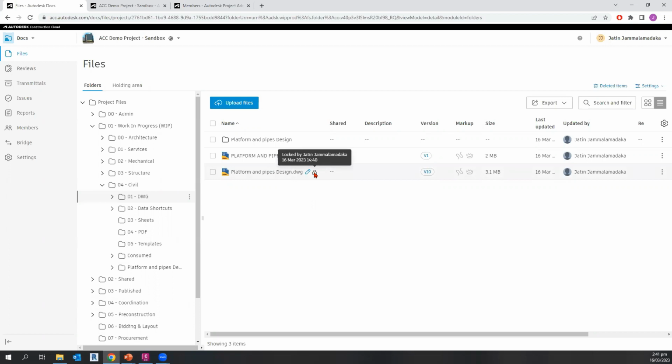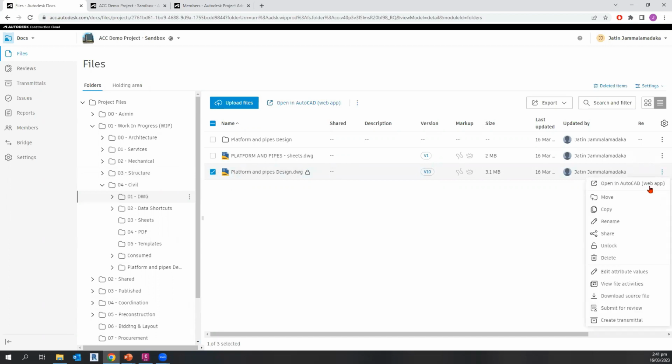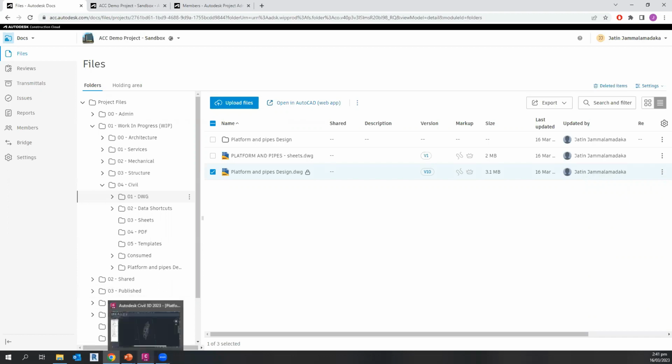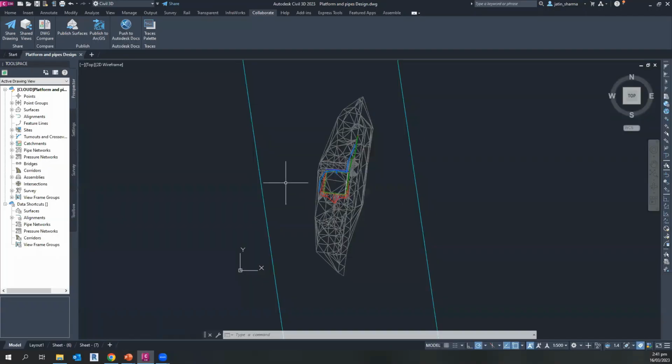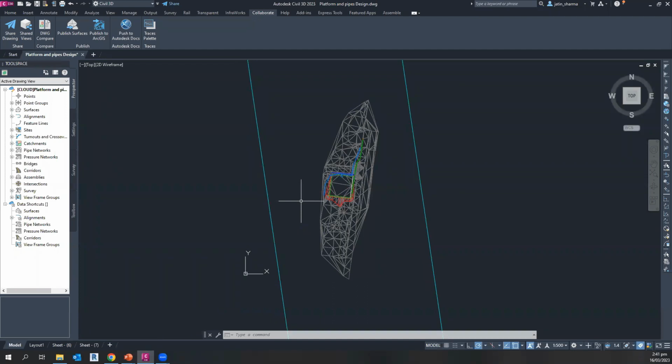It should be unlocked. What you can do is click on this little square next to the file name, click on these three little dots and hit the unlock option. It will boot them out of the file and it will unlock it. Now, you need special permission for this, so your normal users can't just go in and do this every time. You don't have to worry that people are constantly kicking each other out. There is some form of a control permission around this.